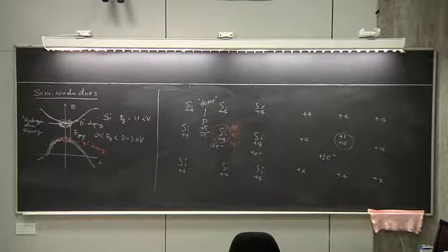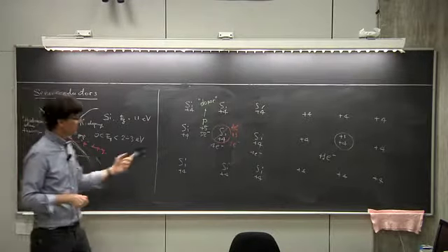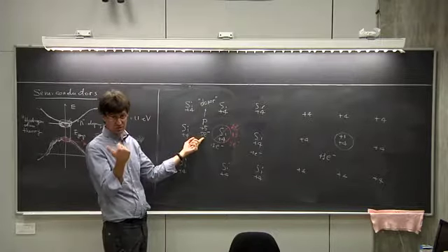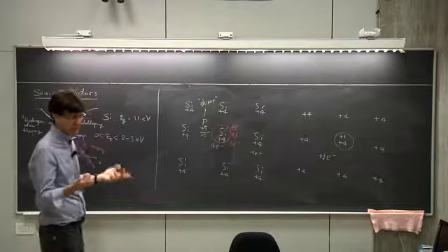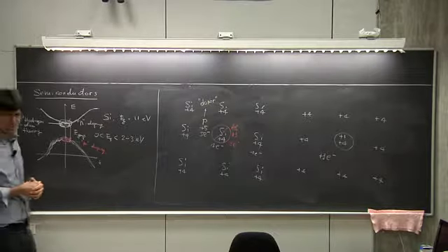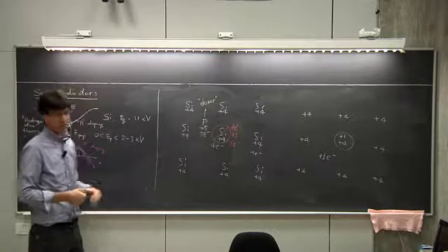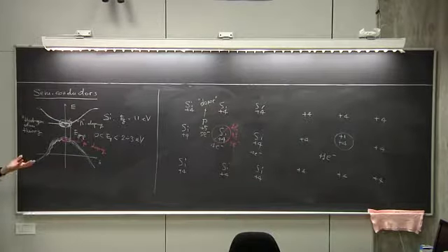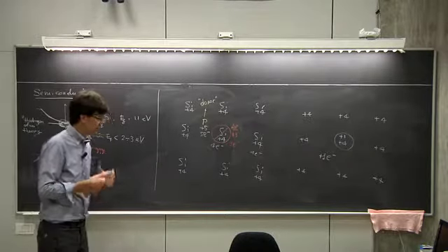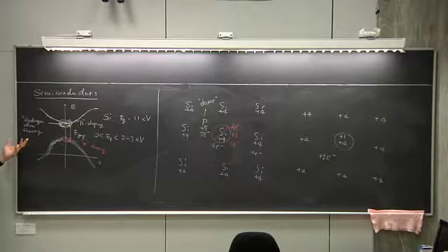Think of oxygen, for example. Oxygen might be considered as a donor because it's on the right side of the periodic table, so it probably donates electrons. So if you don't make sure that your growth takes place at extremely low oxygen pressure conditions, you're going to have something which is N-doped, just because oxygen is always around. So to some extent, it's probably more difficult to grow a perfect ideal crystal of silicon without doping than to grow a crystal with some doping, perhaps unknown.